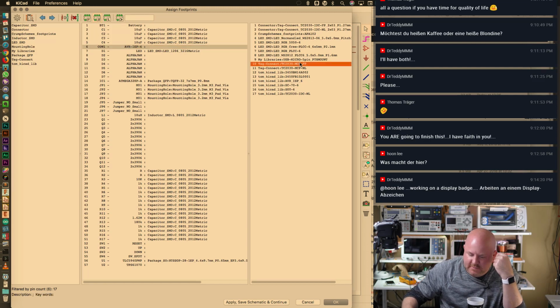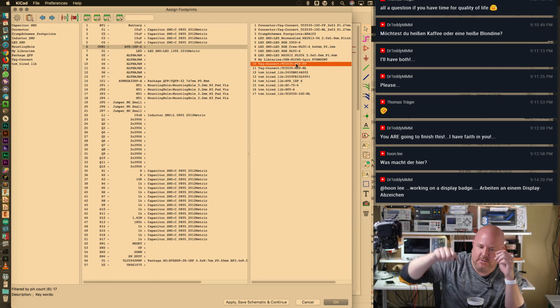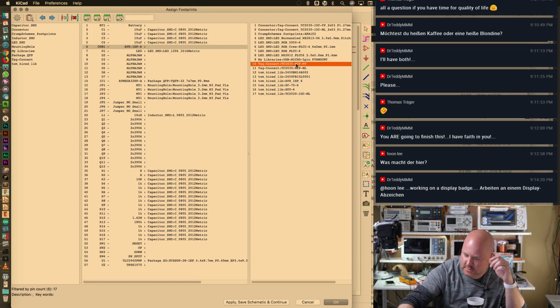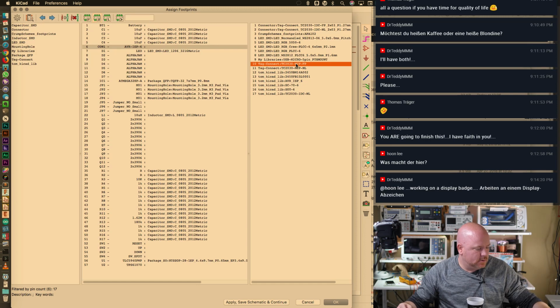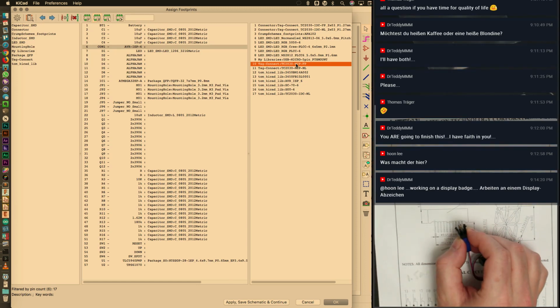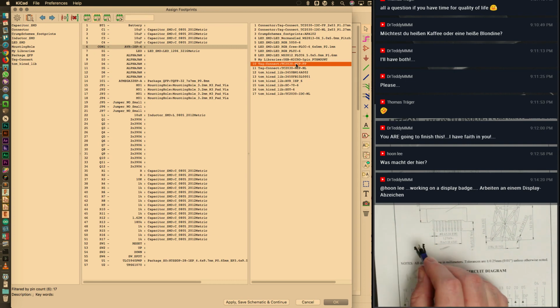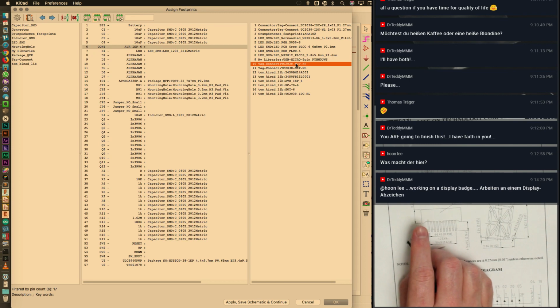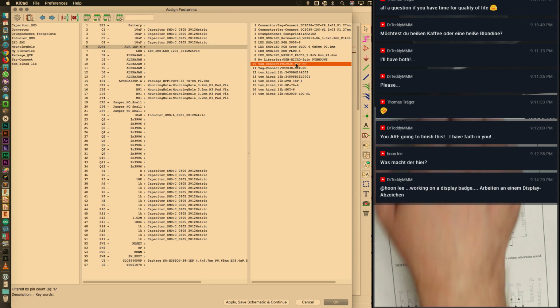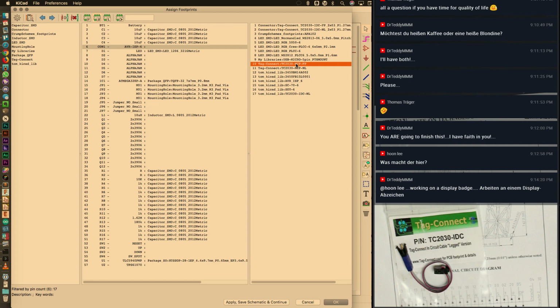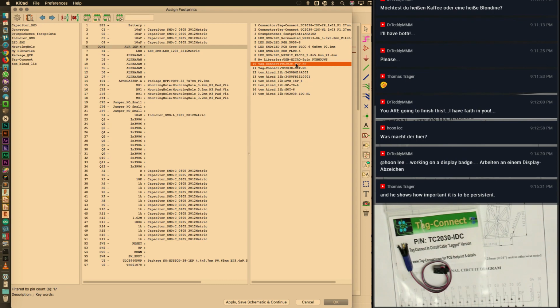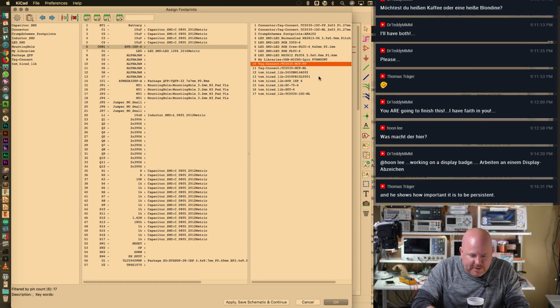And then I did figure out my Tag-Connect, and so to program the microcontroller, I'm using one of these things, which is like a quick connect style thing that just connects to the board and lets go. Earlier in the stream, I couldn't find the right footprint for this. And so I actually went and updated KiCad so that I had the latest libraries, and it was in there. So happy to finally get that figured out.